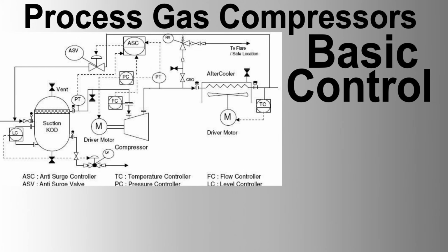#4 Impact on control strategies and loop configurations. A. Load sharing and balancing. The load sharing algorithm adjusts the set points of each compressor to distribute the load. The master controller monitors overall system demand and dynamically allocates set points to each compressor. Ensure the VFDs of all compressors are coordinated to maintain balanced operation.